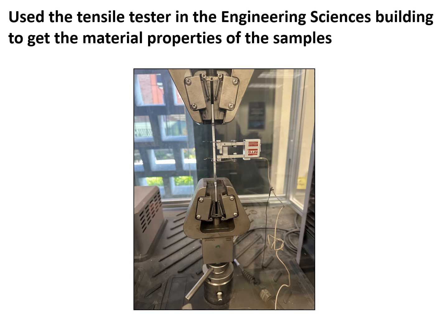This method allowed me to get the force applied to the load as well as the change in distance over time of the material. However, there is a more accurate method to finding the change in distance of the material, and that is to use the extensometer. It is attached to the material like shown in the picture, and as the material is pulled apart, the extensometer follows the extension of the sample, allowing for a more accurate measurement of the change in distance over time of the sample. The data received from the tensile testing of the samples gives the force applied to the sample over time as well as the change in distance of the sample over time.